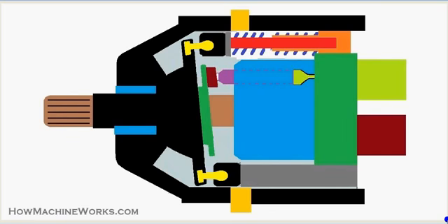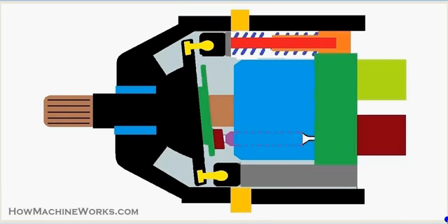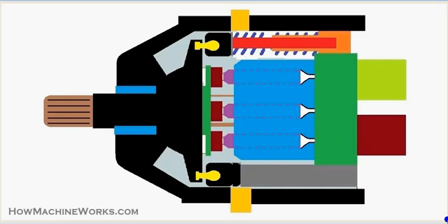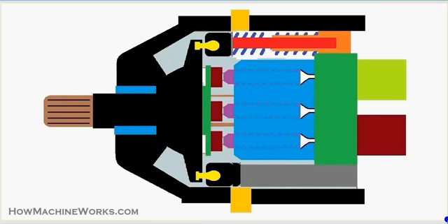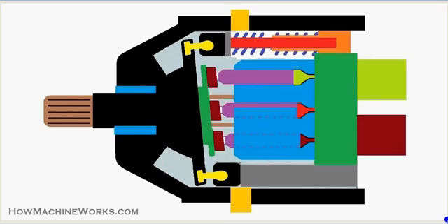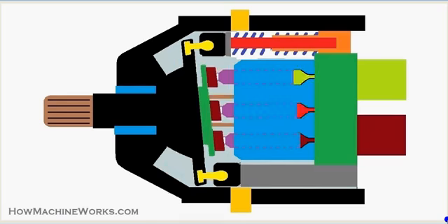So let's say it again. Suction is happening, discharge is happening, suction is happening, discharge is happening at the bottom. So that's it. So we have more number of pistons at the bottom and top. You can see how it exactly works. We have a suction at the top and we have a discharge at the bottom depending on the swash plate angle. So that's how an axial flow variable displacement piston pump exactly works. The variable displacement happens according to the difference in the swash plate angle. So I believe you got an idea about it.